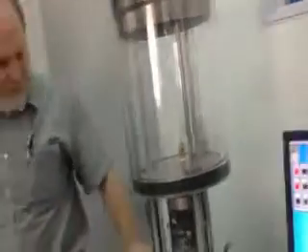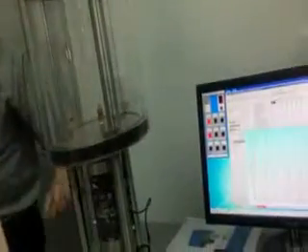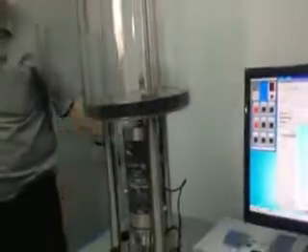When you're doing a test at high temperature, you want to check this air flow. Is it coming out or sucking? This is coming up, and that is a return. It's flowing, not sucking, though it might be a little bit. But if you feel this one, it's a lot higher. This one is up, and that is low.